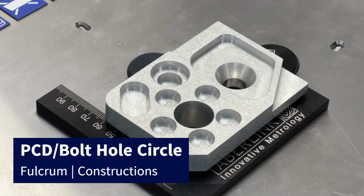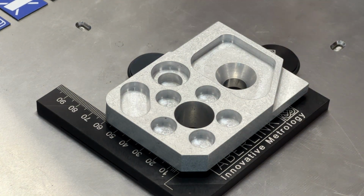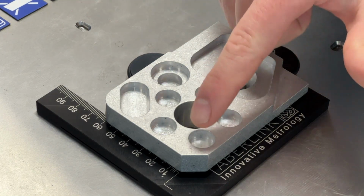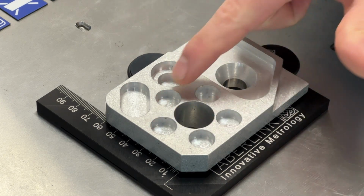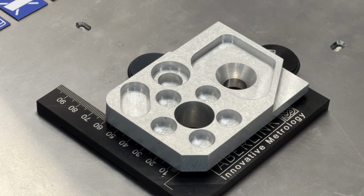In this next example we're going to cover a PCD construction. So PCD, often referred to as bolt hole circle. PCD stands for pitch circle diameter. We're basically going to measure each one of these individual circles, but then construct a single circle that runs through the center of all 5 circles.